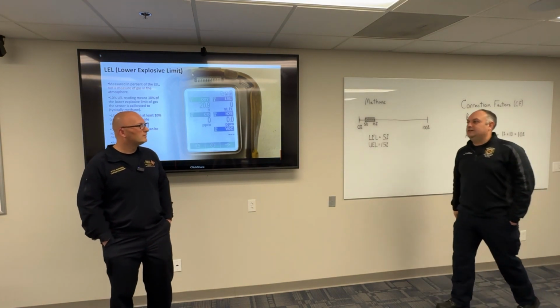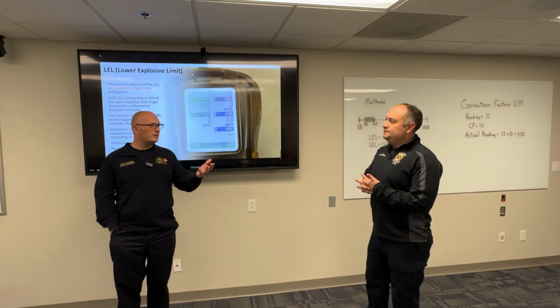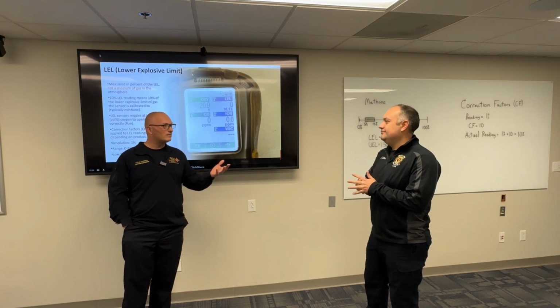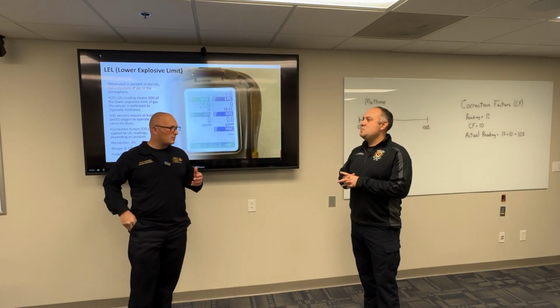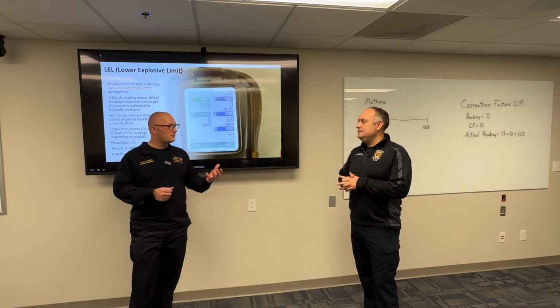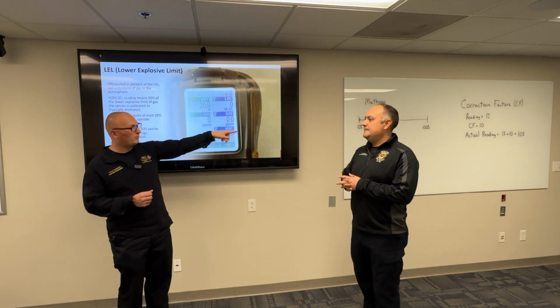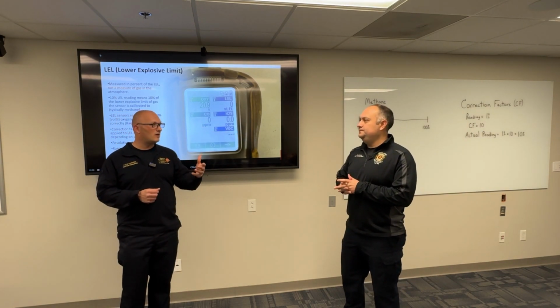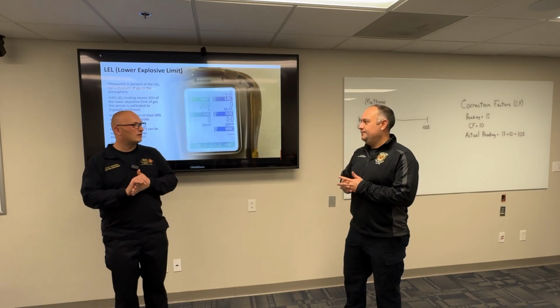Of your LEL? Right. Okay. Right. And where are we going to find this stuff? Like you said, it goes back to reading your manual, right? Yep. Like knowing your product. And I know you and I discussed before, when we were setting a lot of this up, that on some of your meters, you can go in and set these correction factors. So that's one of those things. You really need to know your meters, know what you're getting off the truck with, and how these things are set up, because that's going to help you really determine this stuff. And if I don't know how these are set up, I could get false readings and go down a wormhole that I don't need to go down.